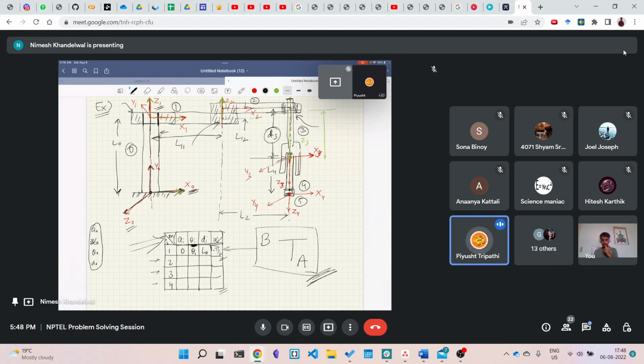It's not parallel to the base, but it is circulating over the base, something like that. Yeah, it is rotating like this. So your base and this link one is going around like this. So Z0 shouldn't be parallel with the pillar or the link one.